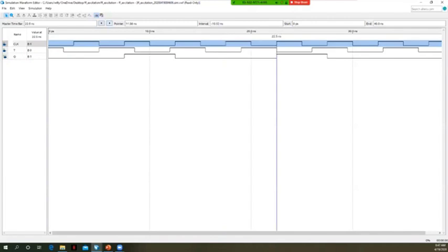I have something bad in my simulation here. At this clock edge, it looks like T is transitioning. So we don't know exactly where this was sampled, but we're going to say T was a 1 when this decision was made, because we can see that Q actually toggled. So I've not set up the simulation the best way, because we try not to have these states changing at the same time. The idea is you don't want your input state T to change at the same time you have a clock edge. So that's why we had that behavior here.